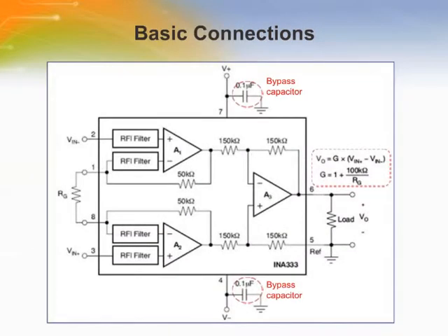The figure shows the basic connections required for operation of the INA333. Good layout practice mandates the use of bypass capacitors placed close to the device pins as shown. The output of the INA333 is referred to the output reference voltage terminal, REF, which is normally grounded.